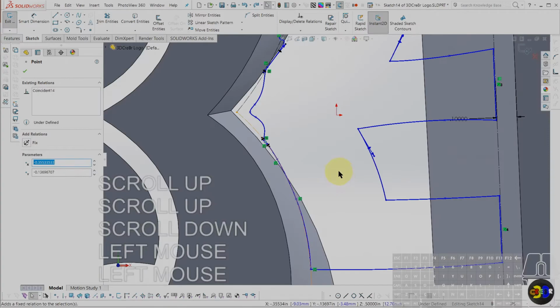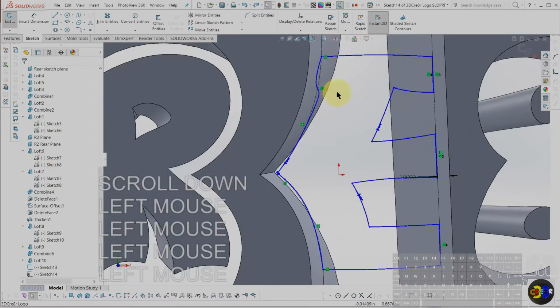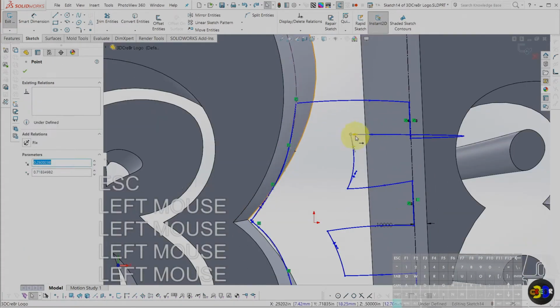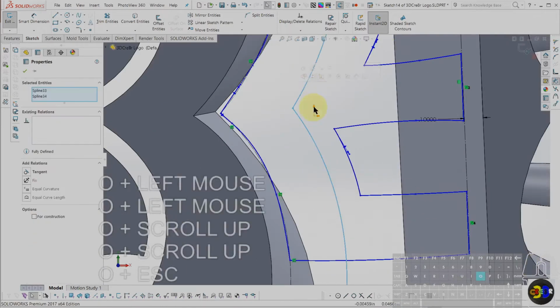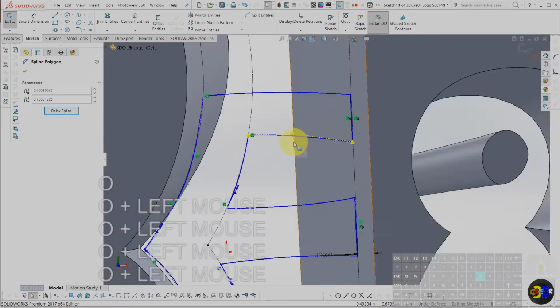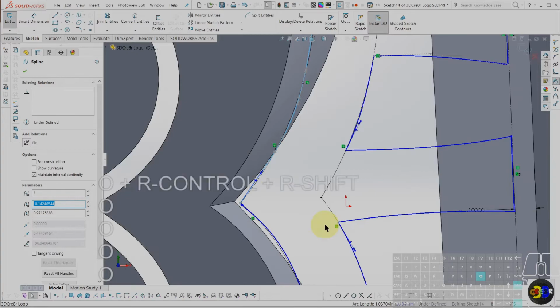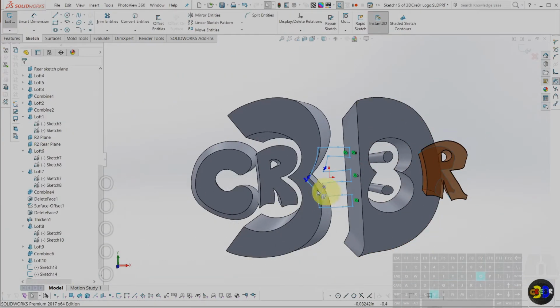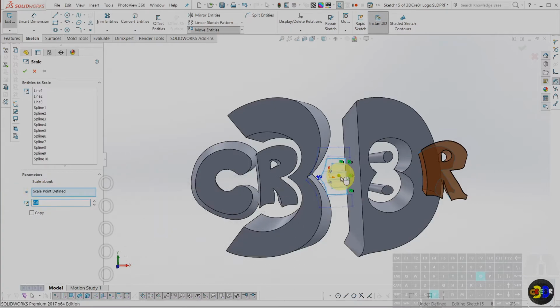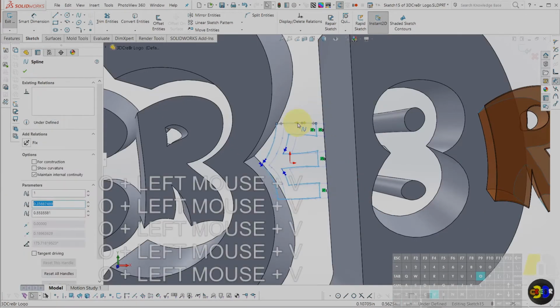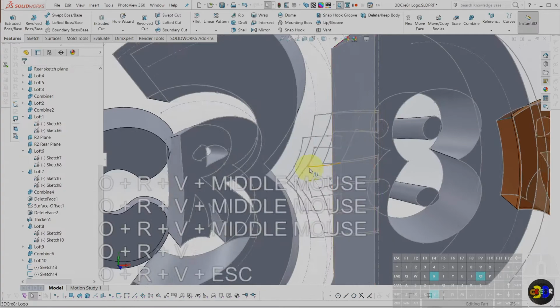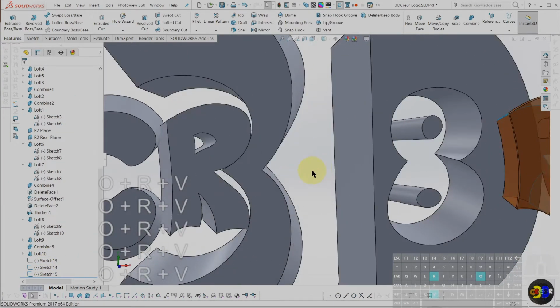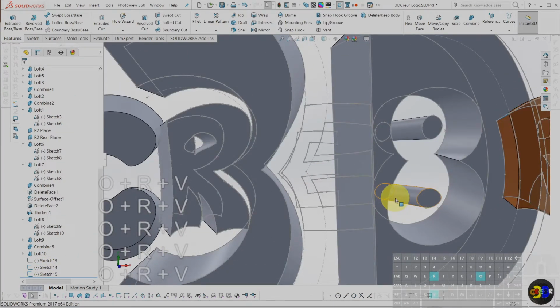And I'm going to make this in front of everything else. So I pre-select that, the front plane, excuse me, and Control plus creates a plane, and a half inch, sure, we'll call that good enough for now. I can always adjust that later because it's SolidWorks. Or I guess I could in AutoCAD too, just not parametrically. I would just do it manually. That's all good. Enter.